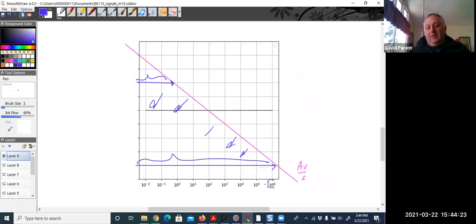And even though we have really good oscilloscopes, it can be quite difficult to measure at a megahertz, not because the equipment is bad, but basically this capacitor has a resistor and an inductor along with it.